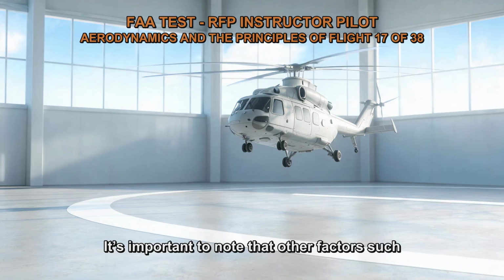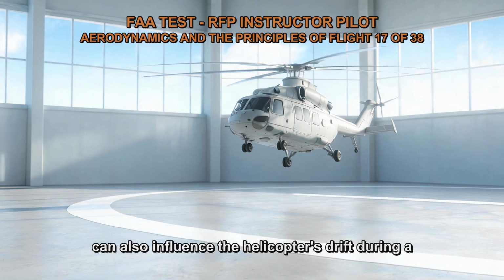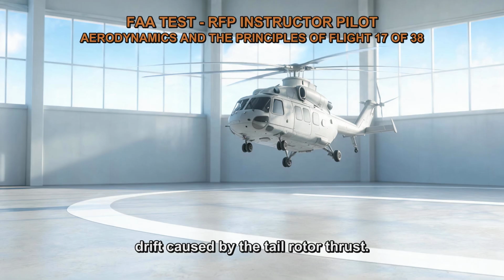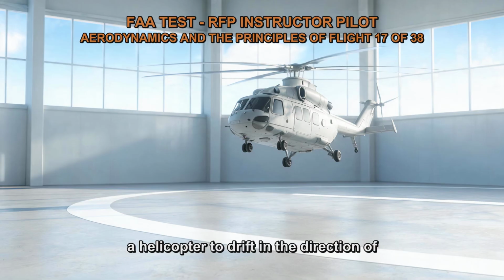It's important to note that other factors such as wind conditions, ground effect, and pilot inputs can also influence the helicopter's drift during a hover. However, translating tendency specifically refers to the lateral drift caused by the tail rotor thrust. Therefore, the correct answer is the tendency of a helicopter to drift in the direction of tail rotor thrust during a hover is called translating tendency.